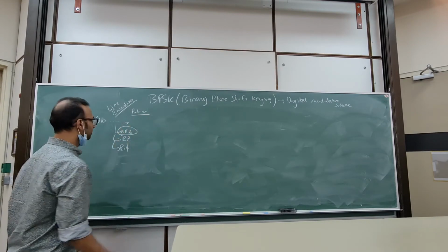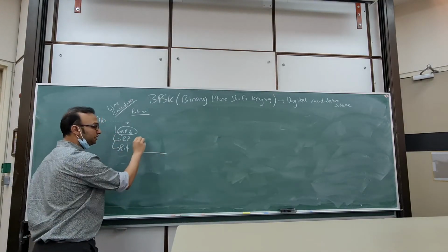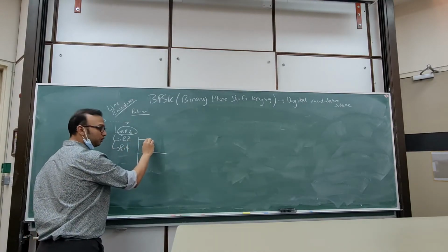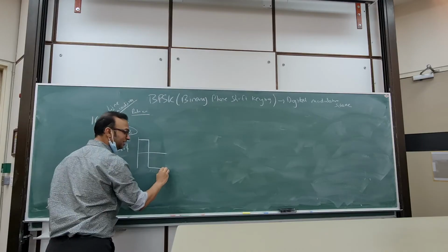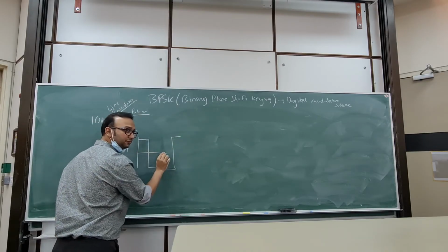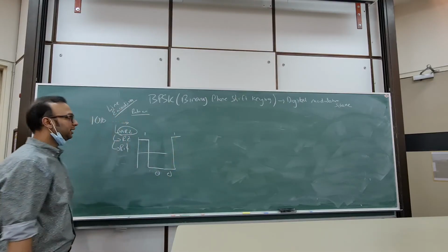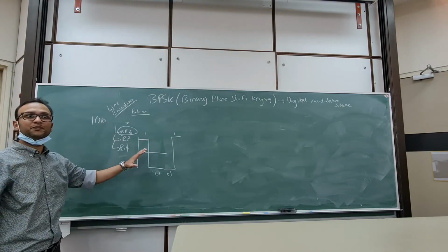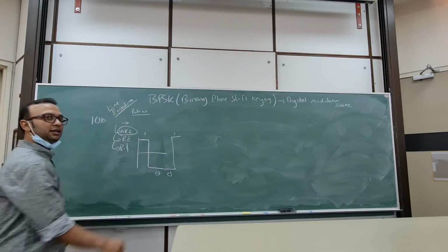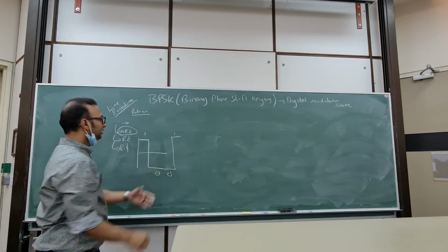What it means is ones and zeros are changed to pulses that don't return to zero. So if it's a 1, it will be high. And if it's a 0, it will be low. So again 0, low. 1, high. So it will not return to 0. So this is 1 0 0 1. So bits are changed to pulses using line encoding, right?